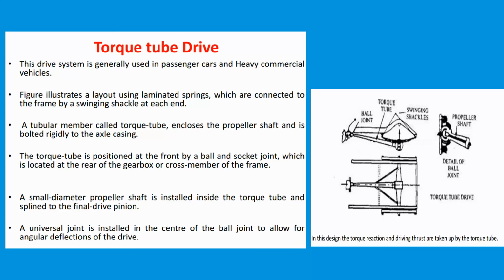Since the torque tube does not constrain the car's body to the axle in the lateral direction, a Panhard rod is often used for this purpose. The combination of Panhard rod and torque tube allows easy implementation of soft coil springs in the rear to give good ride quality.